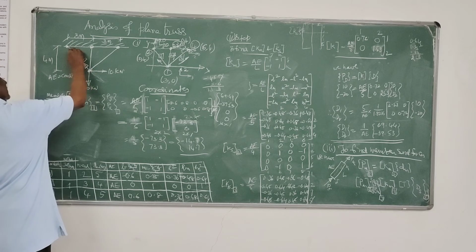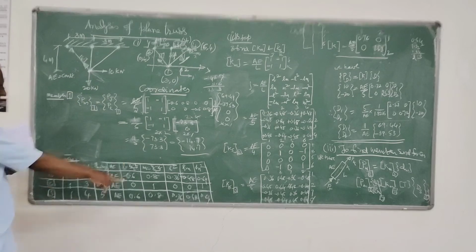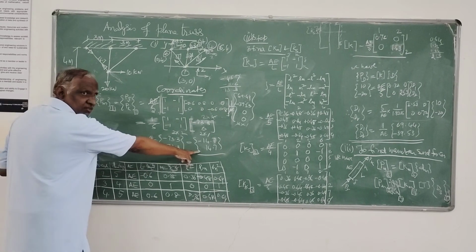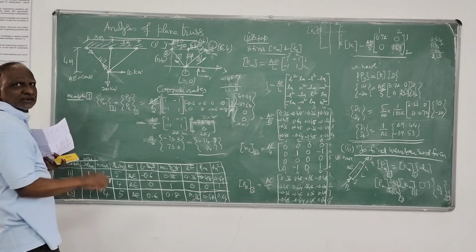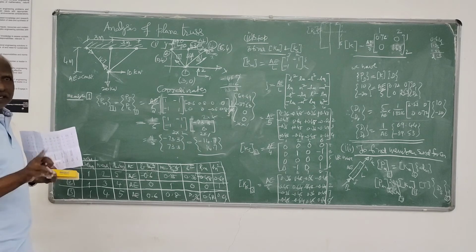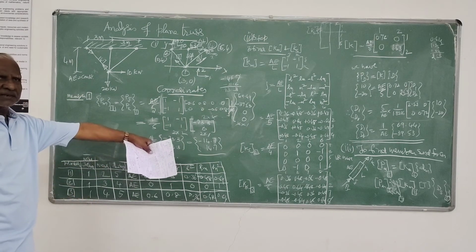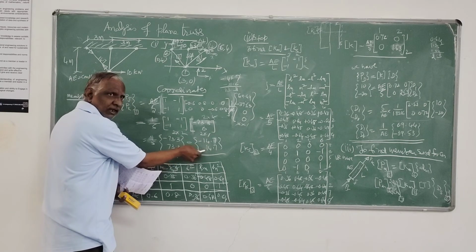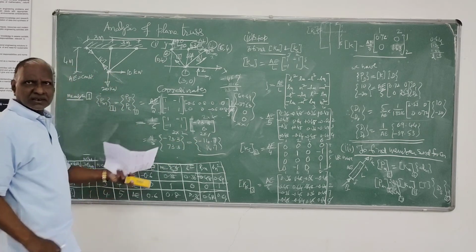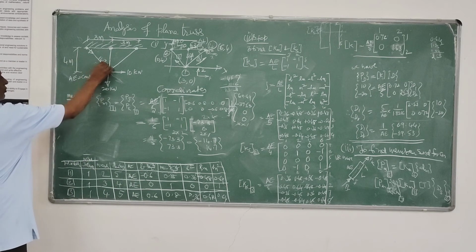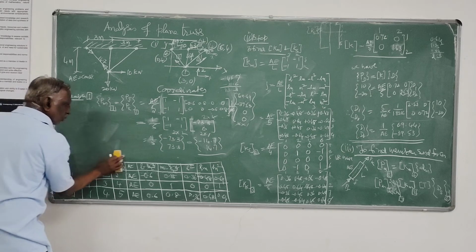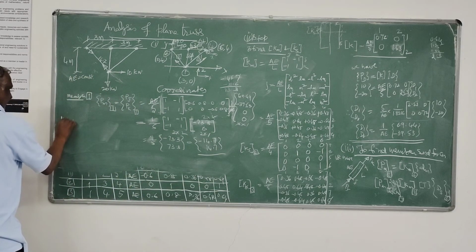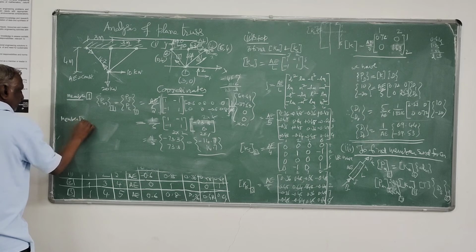It is tension. So this also will automatically be tension because it is opposite. Here it is plus 14.7, plus means it is in this direction, so this has to be opposite. So this is tension. Is it clear how to find the member end forces from that? Here always make sure they will be equal but have opposite signs. That's all. This is with respect to member 1. So the force in the first member is 14.7 kilonewtons, tensile. Then we can take members 2 and 3. Member 2 I will determine, and member 3 we can find on the same lines.